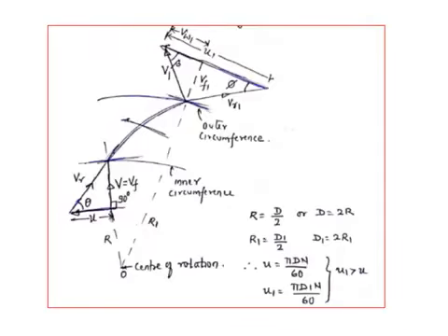Again, I have discussed this, you should know that this is very important. So the velocity triangles have to be written properly. This is the inlet velocity triangle. For best efficiency, the water always enters in the radial direction. As the water enters, the vane would have moved with some velocity, therefore VR is always in the tangential direction. So V is always in the radial direction. So beta is 90 degrees, this is the vane angle at the inlet.